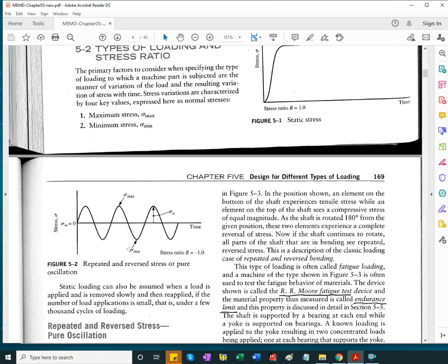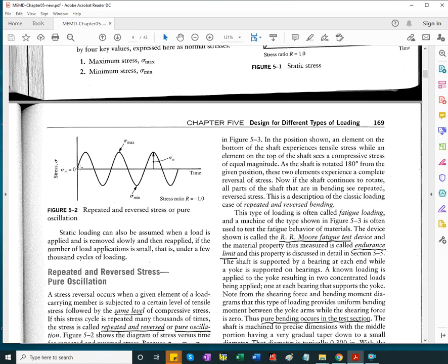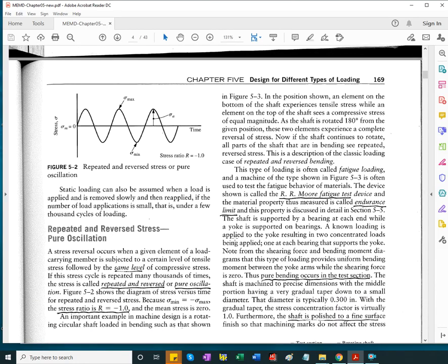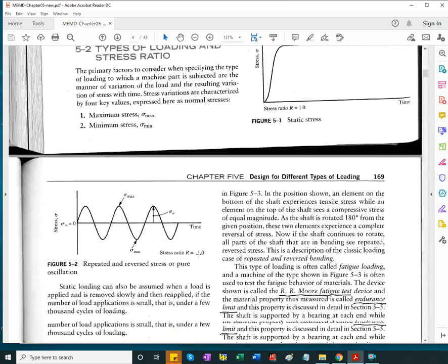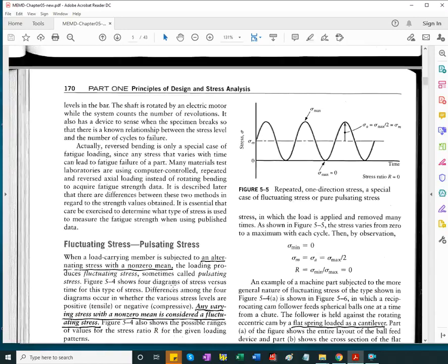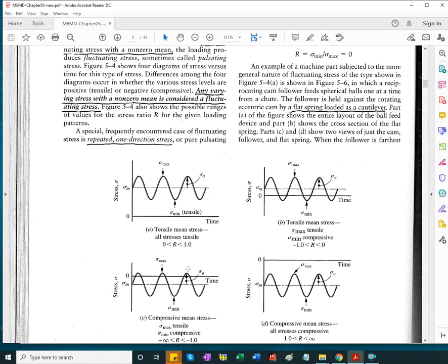Graphically, the fluctuating stress can have this appearance, where it varies the same amount about a zero mean. I'm telling you now, this has the most damaging effect upon the material. When you want to break a wire, what you're doing is bending it back and forth the same amount in both directions. And then, in terms of stresses, that corresponds to R equals -1.